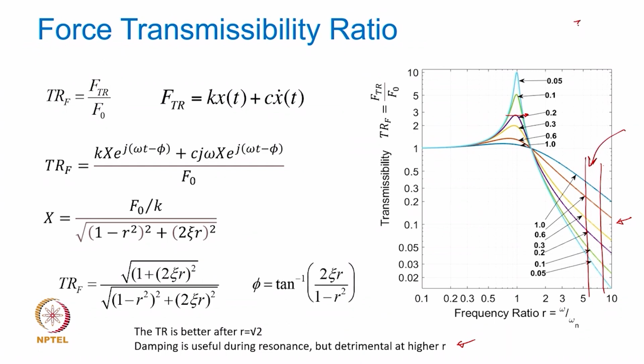The structural damping ratio for steel, as we know, is roughly of the order of 0.005 or 0.01 at the most. So the upper limit could be of this order, and with that you will be really comfortable here.